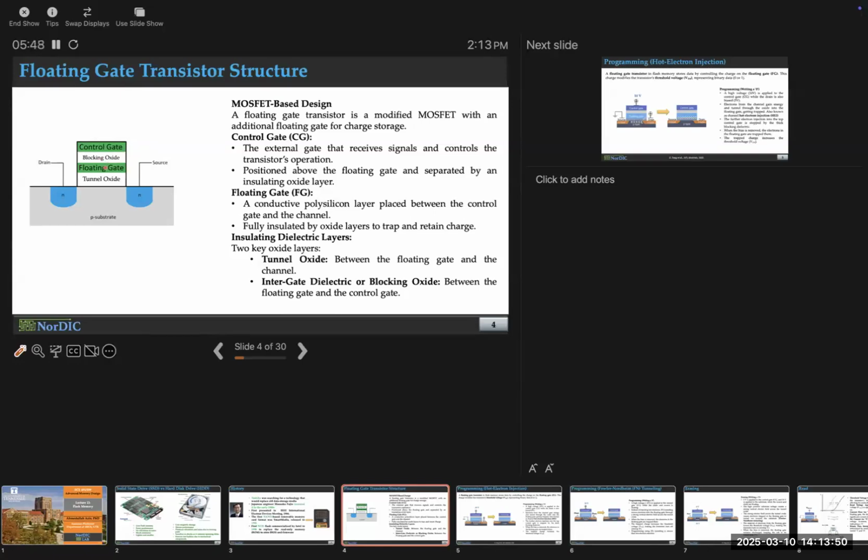How many of you remember that in MOSFET, the threshold voltage is affected by the charge at the gate? Do you guys remember that? Where did we discuss this concept? So if you have a positive charge at the gate, somehow stored, that affects the threshold voltage. In ferroelectric memory, remember, that was the whole point of ferroelectric memory. When you make the ferroelectric layer positively charged or polarized, it affects the channel in a way, versus when you make it negatively charged, it's affected in a different way. So your threshold voltages will be different for positive and negative charges.